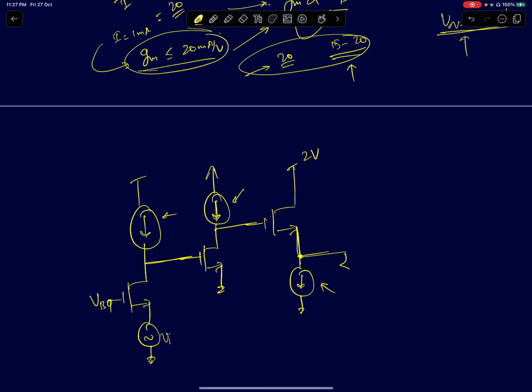So now you have a resistor RL here. We have to talk about how I am going to choose my W/L ratios and all that. Now it's given that the total swing that you're supposed to design this circuit for is 0.8 volts, which means around some DC voltage, let's call it VODC, the output DC voltage, it has to swing 0.8. Let's assume it is symmetrically swinging, so 0.4 volts above and 0.4 volts below VODC.